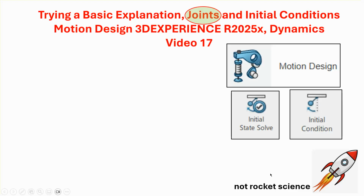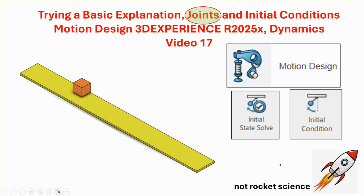Now, within motion design, when you have, for example, a dynamics scenario, a rigid body dynamics problem, you can specify initial conditions, both velocity and position, and then you can display that on the screen by using the initial state solve icon. I will do this in the context of a very simple problem, a prismatic joint.